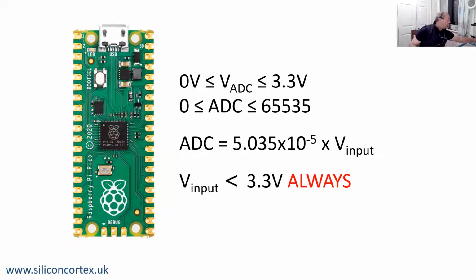It's the SIM800H. 3.4 volts it starts at. If you put 3.4 volts from this into the Pico board, there's a very good chance that it will hang. I had all sorts of weird problems with the code suddenly hanging, and I couldn't work out why. I thought there's nothing wrong with the code, so I eventually tracked it down to the RP2040 having no voltage tolerance for being above the supply rail, so that's quite key.